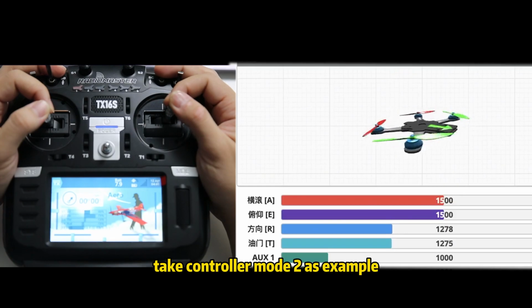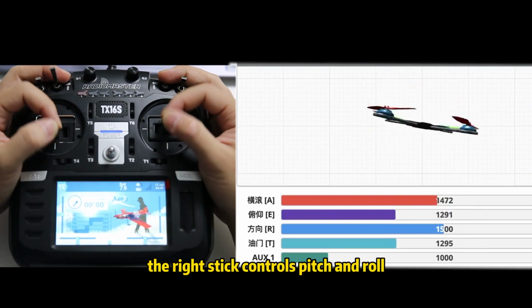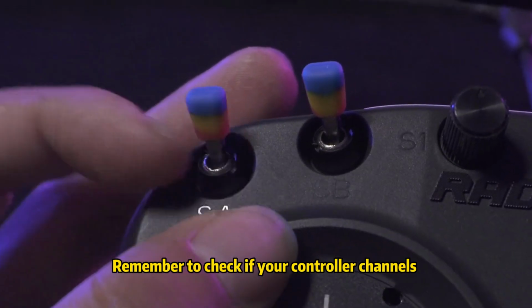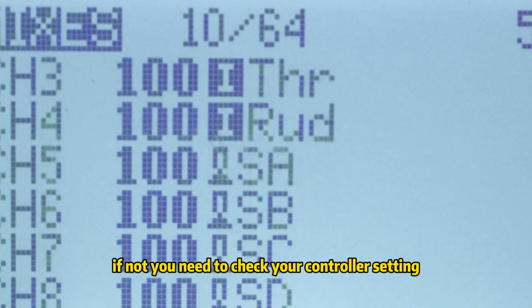Take control mode 2 as an example. The left stick controls the throttle and the yaw. The right stick controls the pitch and the roll. Remember to check if your controller channels are displayed as output there. If not, you need to check your controller settings.